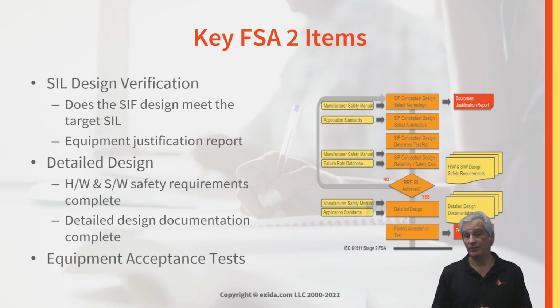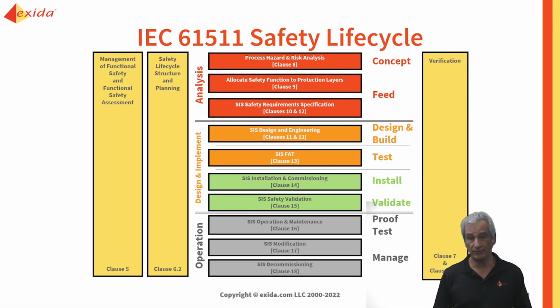Also at this stage we may choose to do some preliminary cybersecurity assessments to see that if we're using barrier devices or switches, that everything's hardened properly, it's not susceptible to potential incursion or malware, for example. Firewalls, have they been set up correctly? Do they have the right rule sets and so on?